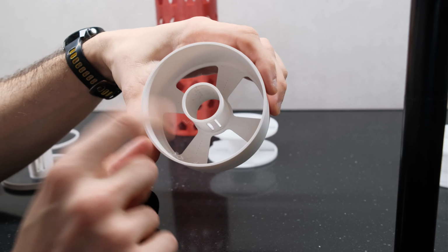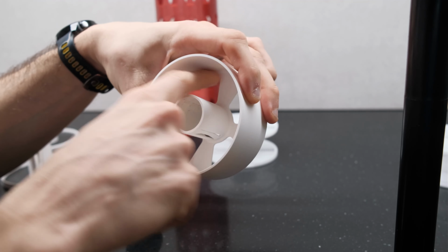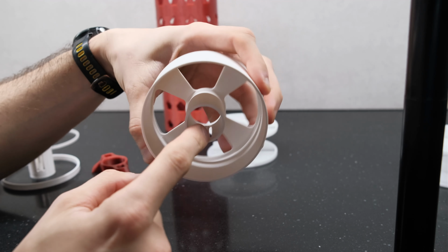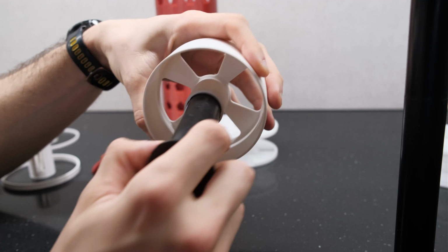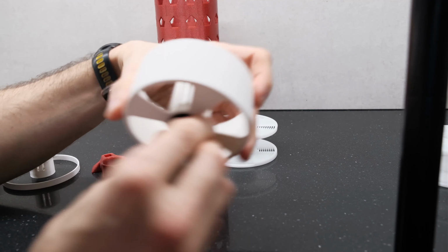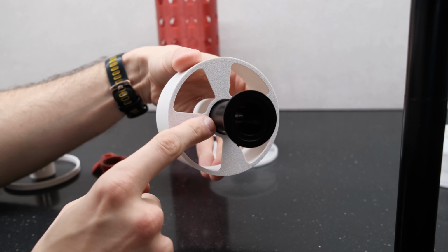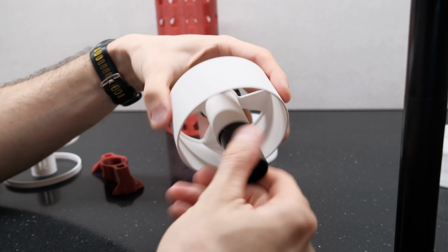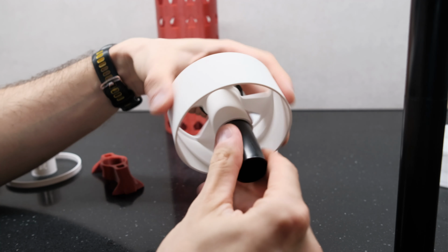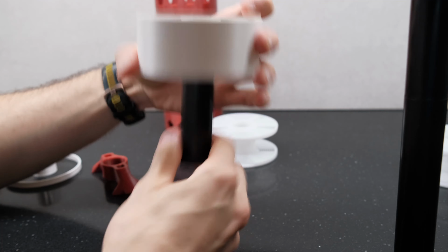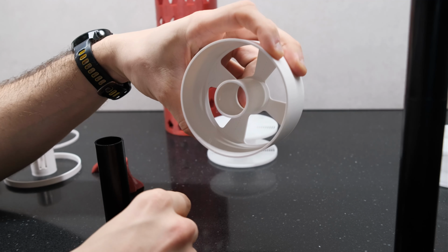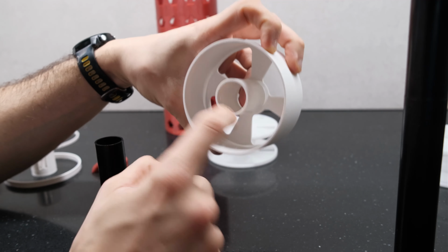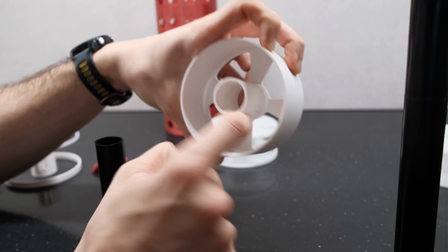I will show you how the design looks on a computer, and you will understand my additional thoughts here. I just want to start with a physical example. And also here I have a compliance pin, which works exactly the same. I have the same bevels from the top and from the bottom. And as you can see, it works perfectly without any problems and has a snug fit. It's even squiggly there. And because it's made from plastic, PLA, if this fit doesn't really work or creates some problems over time, you can use a heat gun and bend it a little bit inwards.